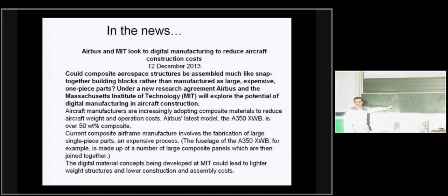If you have 4 parts, whatever problems you have, let's say you connect these two, and then these and these, you can divide the overall tolerance problem among more locations, and therefore at each location you will have less of a gap. So if you do it in a smart way, you don't just connect one and keep on doing that and collect the complete tolerance here.